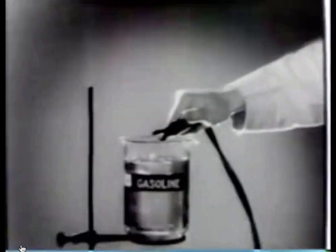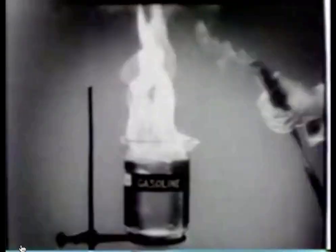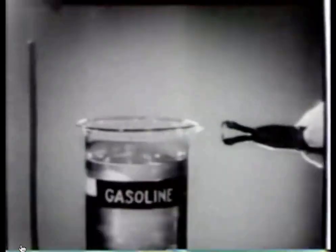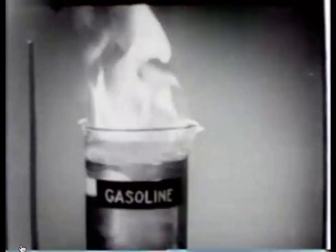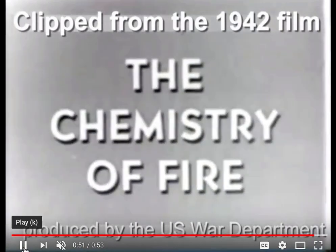And then we put our spark right in that sweet spot where there's enough vapors, and this is the flammability range. So that lower end of the vapors, how much vapor is in the gasoline, would be the lower explosive limit. And we set our meter, when we're monitoring for confined space, at 10% of that value.